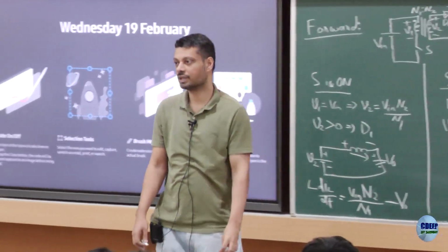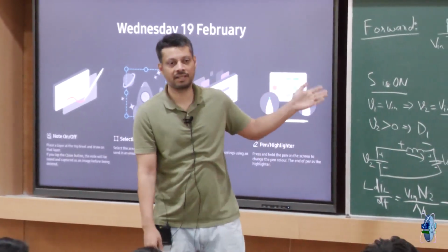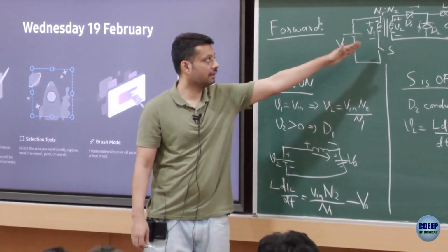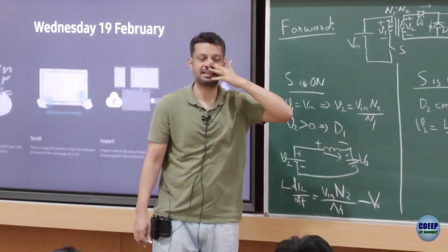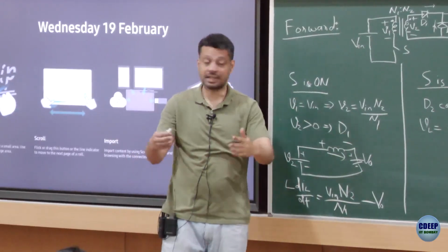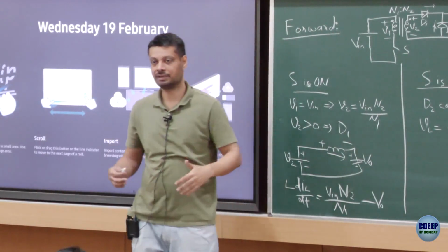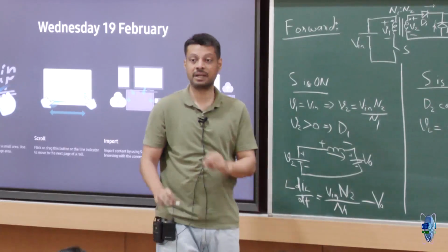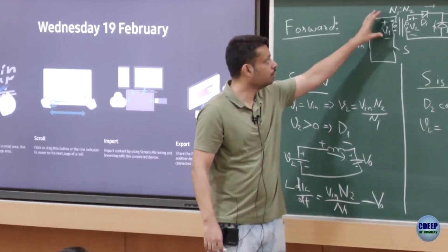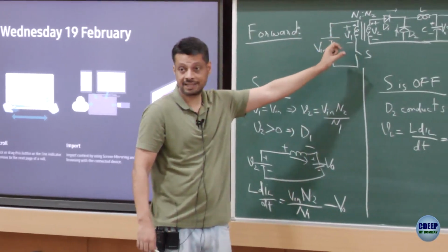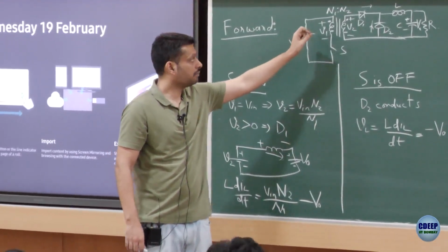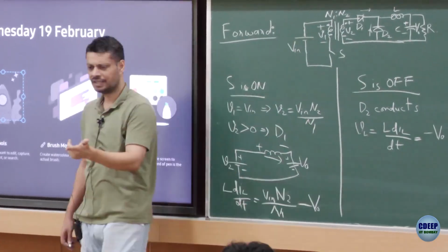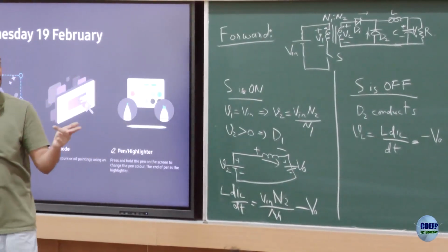Okay. So what he is saying is, look, what we are drawing here is ideal. Of course, in reality, you can never have an ideal transformer. So in reality, you would have a magnetizing inductance, and that actually requires D1. And he has given some explanation of it. The last part is not perfectly correct, but your catch is correct that you require it, because eventually there is going to be a magnetizing inductance, and in that case you need D1, otherwise things will not operate as you want. Anything else you want to add? Anyone else wants to add anything?